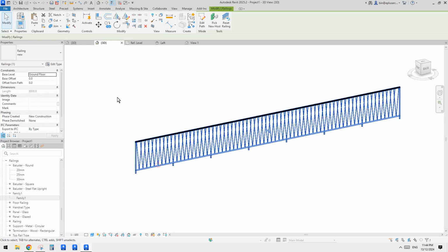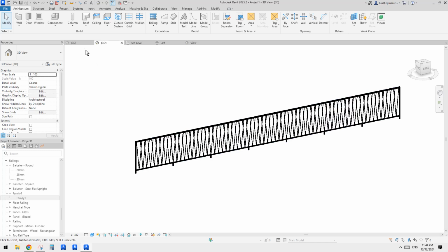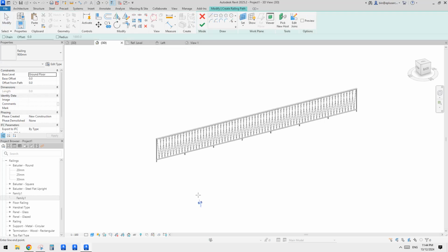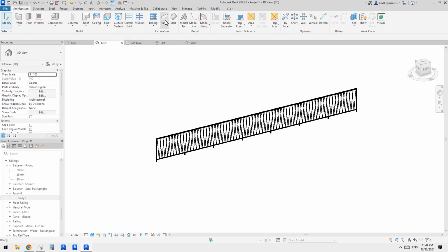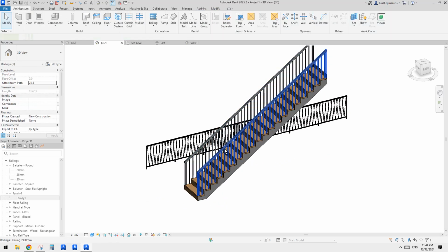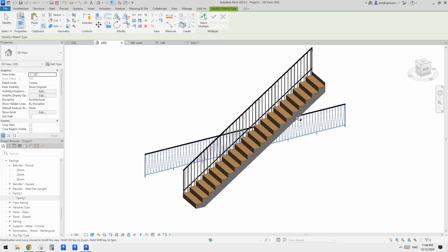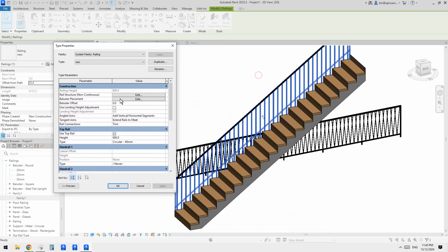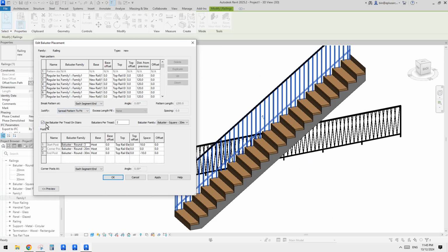And also because we used a baluster panel with slope angle already in, it's possible to place it on stairs. I'll just do this one, and maybe I'll delete one. Match. Okay, so it's not working. So for now, currently we have the setting here. See, use baluster per tread on stairs. Currently using these square 20 mil, so 2 every tread. We just need to change this one.